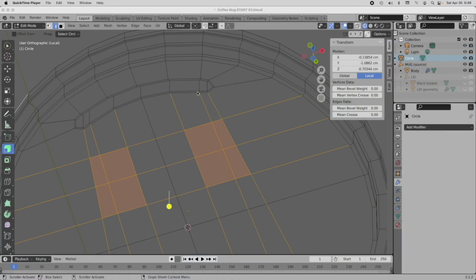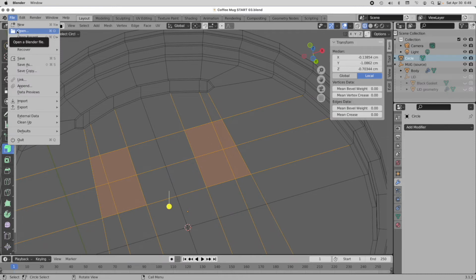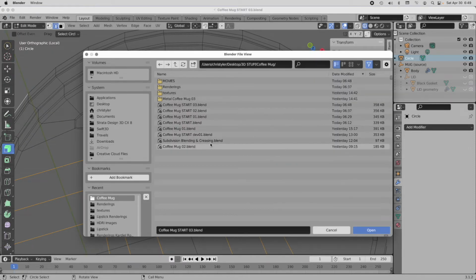Dividing small polygons into larger polygons, especially if there's an irregularity, is going to tend to pull the curvature into this flat area. If you want to maintain that flat area, then you need to add a crease on that boundary polygon so it doesn't subdivide past that. So I'm going to pull up a simple file that demonstrates this. Conceptually, it's very easy to understand.